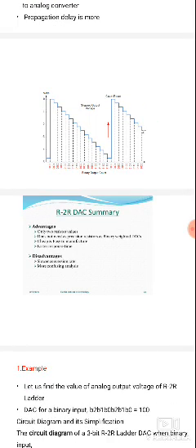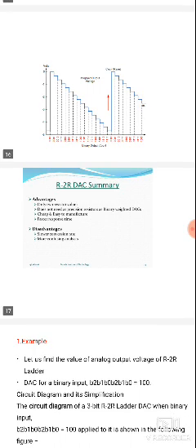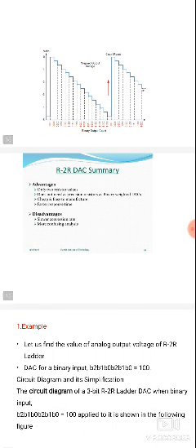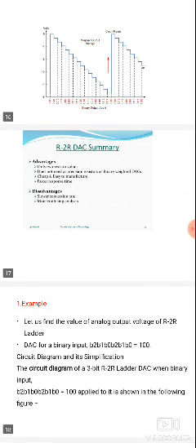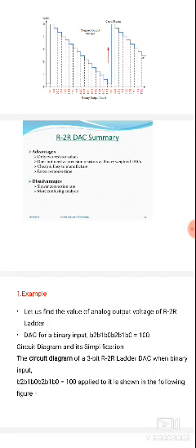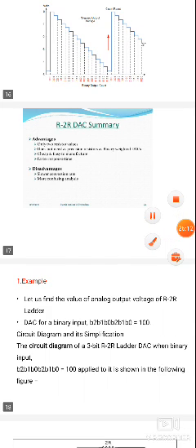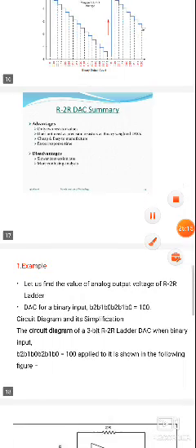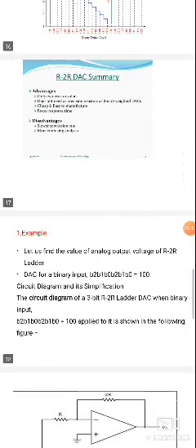In the R-2R ladder digital to analog converter, only two resistor values are used. It does not need the precision resistors of binary weighted digital to analog converters, and it is cheap, easy to manufacture and has a faster response time. The main disadvantages are a slower conversion rate and more confusing analysis.